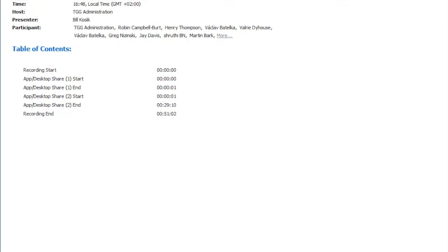So the way that the tool works, the 4 areas are the compressor, which is whatever the compressor power is, whether it's a DX or a chiller; the fan power, which will be the CRAH units or the air handling units, or whatever the source of the fan power is; pumping, and that could be chilled water and/or condenser water pumping; and then the final is the heat rejection device, so that would be a cooling tower or dry cooler. It can be any number of things. Right now, it's hardwired for a cooling tower, just from an energy standpoint. But yes, that's definitely included.